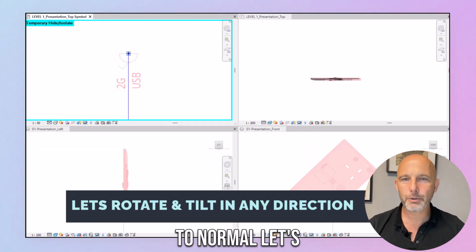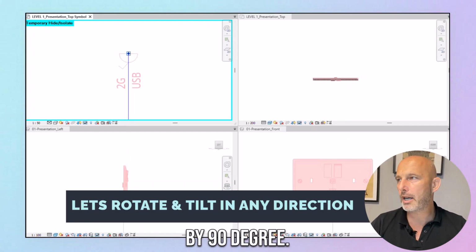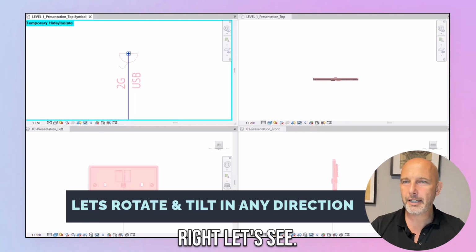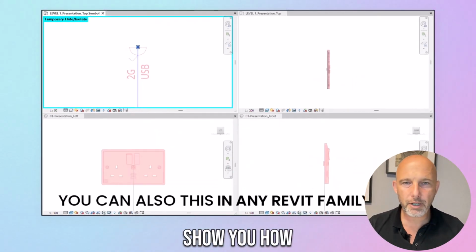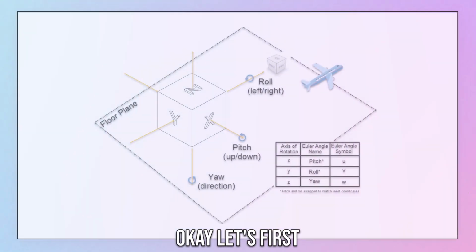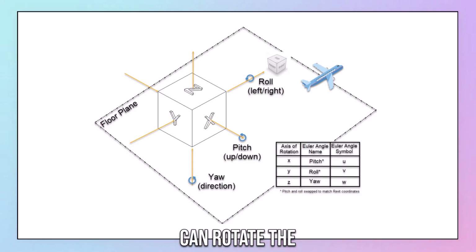Let's go back to normal. Let's just tilt it in the Y plane by 90 degrees. Right, let's see. Sweet. You can do this with any Revit family, and I'm gonna show you how to do it. Okay, let's first start from understanding which axis we can rotate the family on.